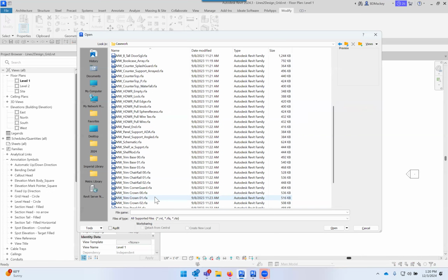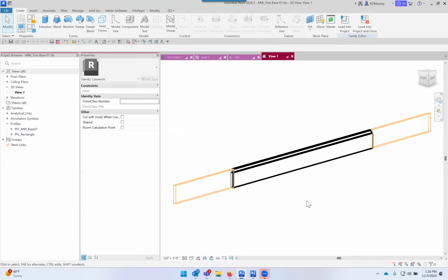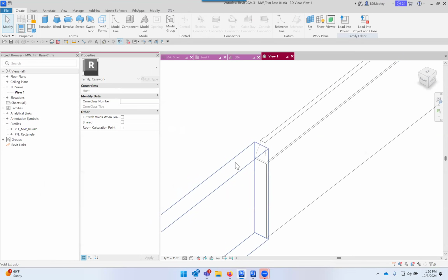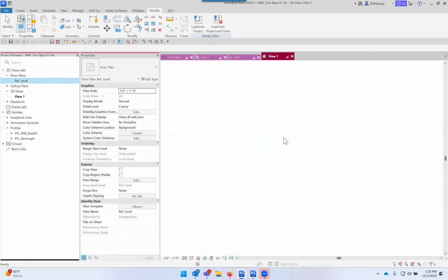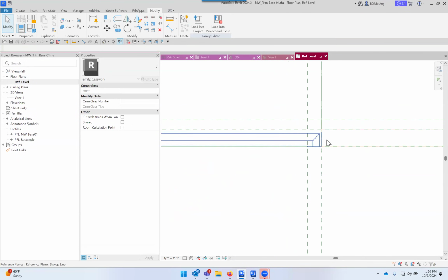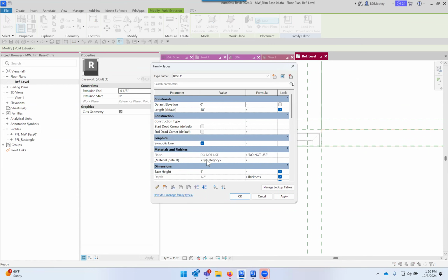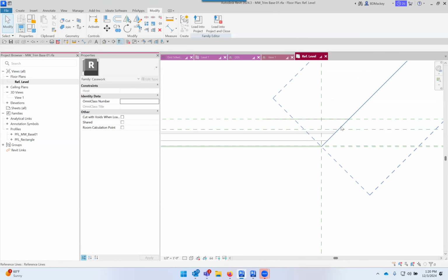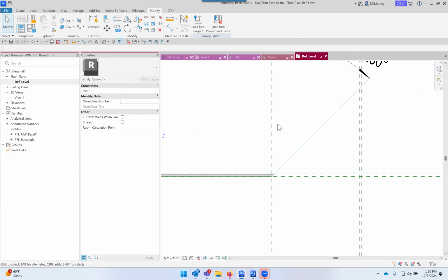So if I come back to my millwork trim, pretty much any one of these will do. I'm not going at an angle, it's not cutting it plumb, but you'll see for any of my millwork, when I start looking at it, I have these voids inside of here. The reason I have all these little nested voids is because if I need to come in here and cut this one off at a 45, this void will then rotate from 90 over to 45 to actually cut that sweep. So if I were to come over here and say that end angle is going to be a 45, the void now goes into action and it goes through here and cuts this void. The void cuts it out. Right. So now I can start coming through here. You'll see that this rotated.